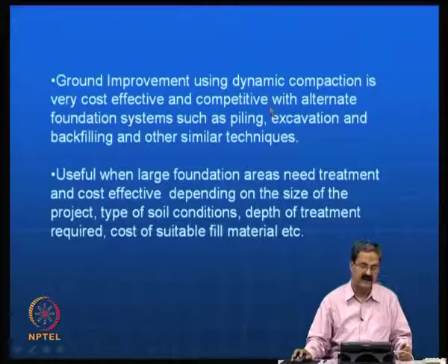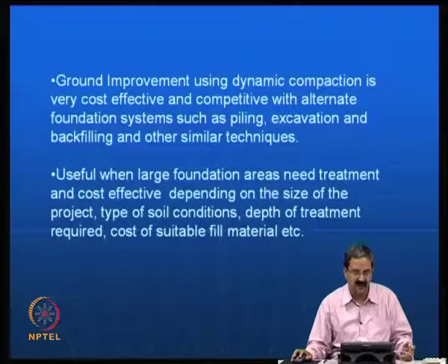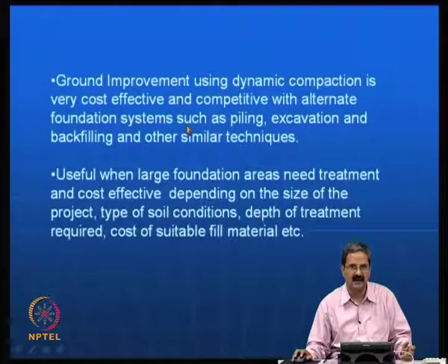So, in this case the technique was very effective and cost effective. In fact, it is maybe 40% cheaper or even 50-60%, because piles are expensive, compared to just tamping, where you do an SPT test and all that.